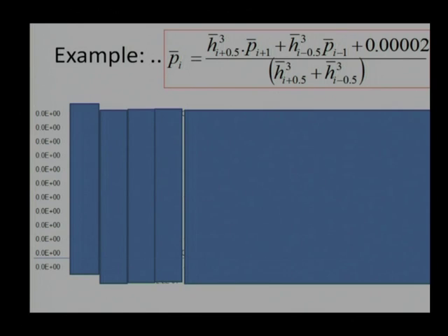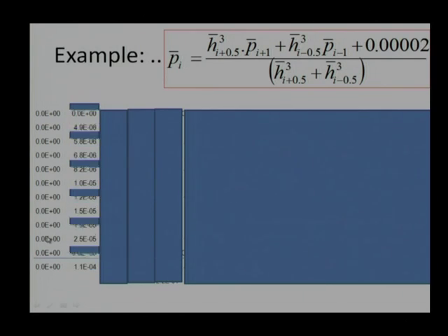As I mentioned earlier, when we do not know initially any value of p, we write the value as 0, and that is indicated here, the 0th iteration. In the 0th iteration, we are using all the pressure values as 0. Then we come to the first iteration, and another thing is that we are using a 0 value of pressure at the entrance and the exit.